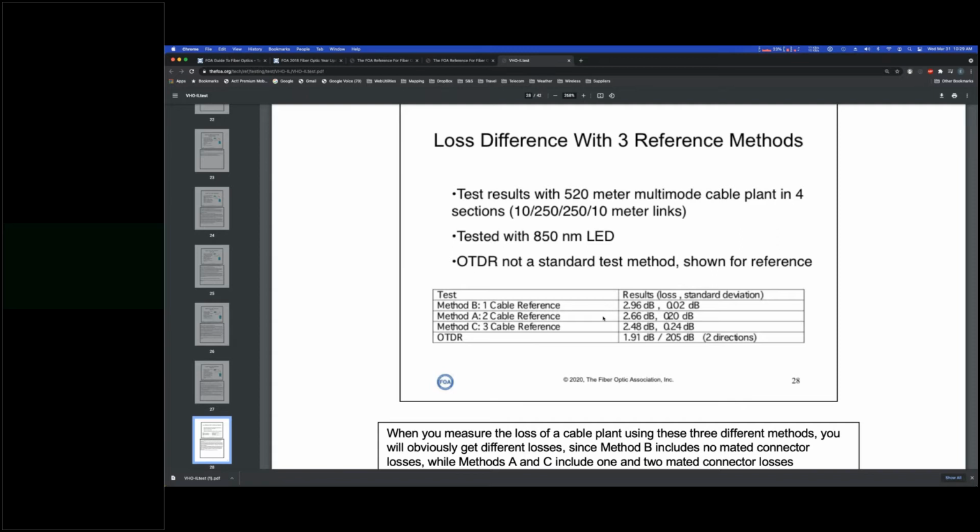There is another reference method on the OLTS called a loopback reference method, which is essentially a way of referencing a single cable to the unit itself. And I know that a lot of folks use the loopback method, and I believe it is accepted by some carriers. I know a lot of contractors use it. I still recommend trying to do a 2-cable reference method whenever possible.